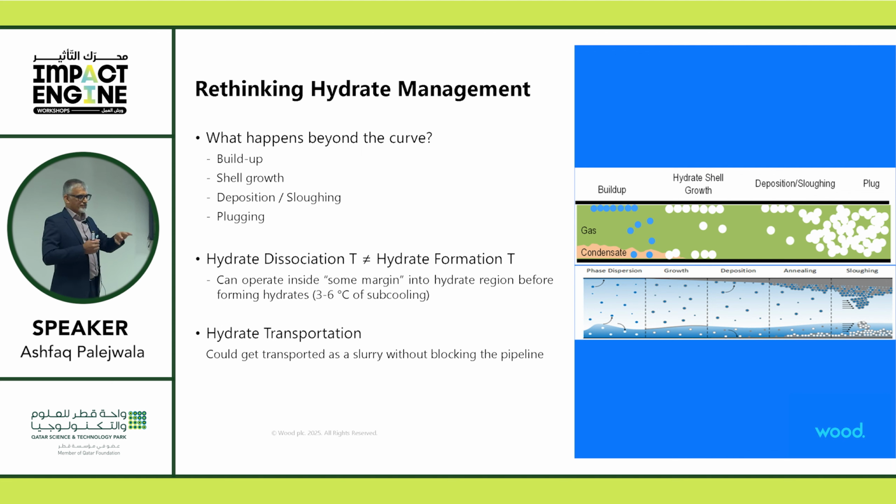Now, as hydrates start forming on the wall, you start getting something like stalactites. You can imagine icicles forming. However, because of the fluid moving, it breaks them. So you get sloughing. So there's all kinds of complicated kinetics built in to hydrate formation.